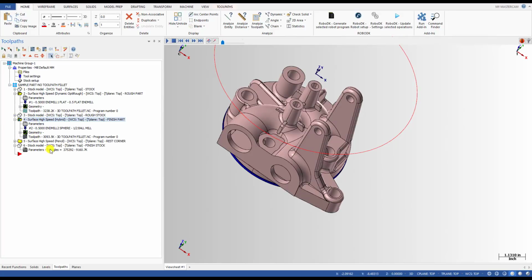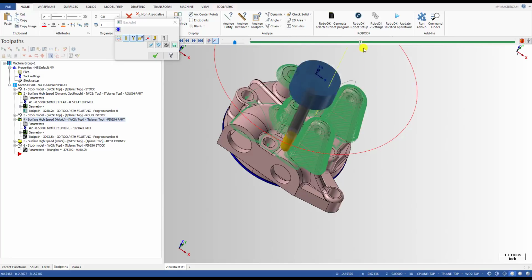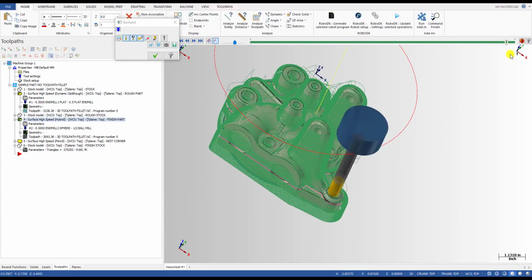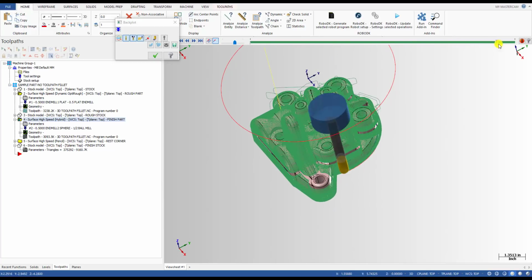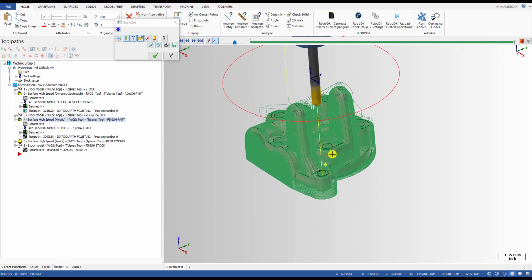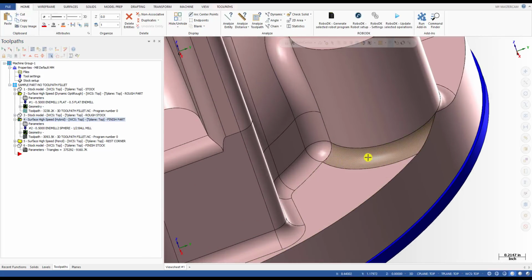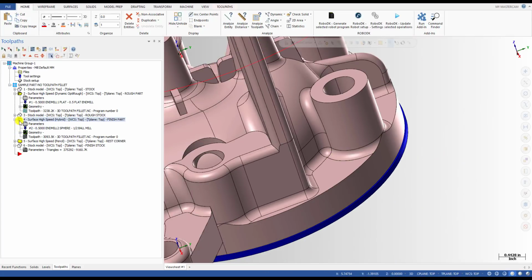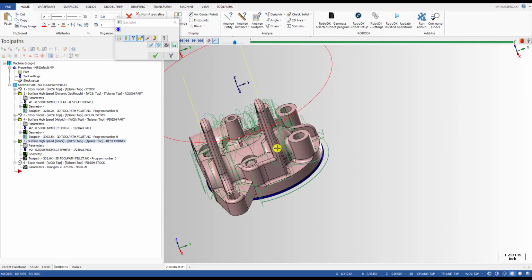And for the finishing I use a hybrid toolpath, because this is just for demonstration, so I don't make this as a real part. I just want to show you how the Toolpath fillet works. So don't ask why I can run this part like this with no collision, and how I can do it. It's just for demonstration. Okay, you can see this is the fillet toolpath, and I use the half inch ball mill, because the tool is too big and the fillet is too small. And after that I clean the corner with the same tool, a half inch ball end mill, with a pencil toolpath.